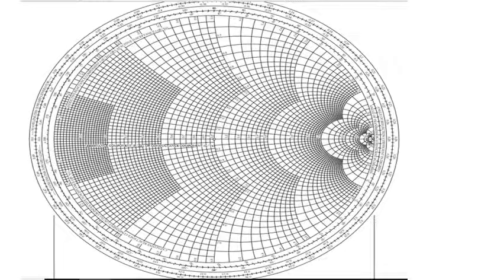To start with the design, as shown in the previous slide, we are supposed to first plot ZL. So how do we plot the ZL point? It is given as 1.2 minus j1.6. 1.2 meaning we are going to take it from this, your center point 1. So 1.2 will come approximately here. I'll just highlight the circle.